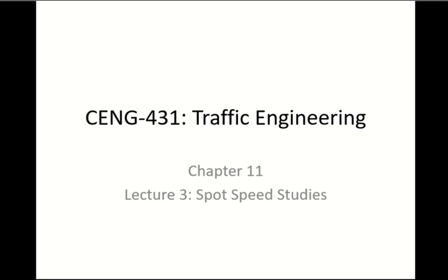It's a spot, so it's basically a point. Spot speed studies mean that you are collecting speed over a spot, a point. To collect the speed over a point or a spot, we should have some radar or a detector or something like this.